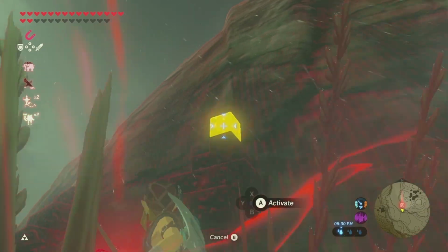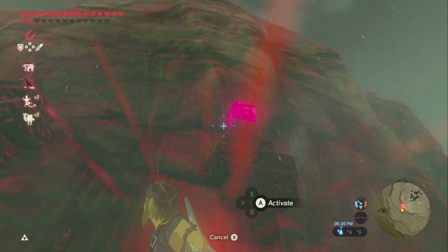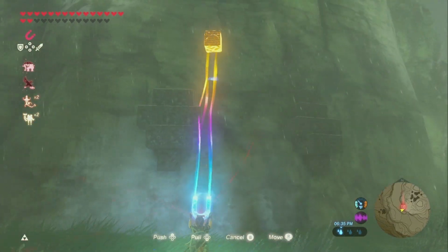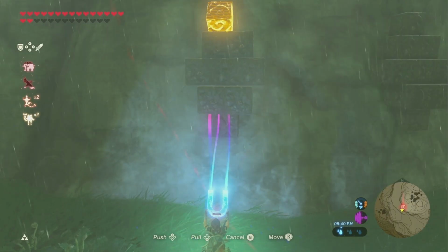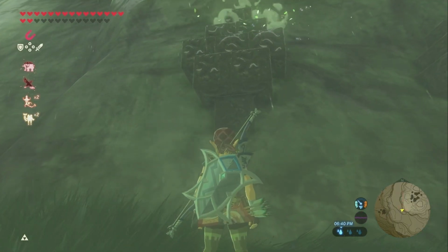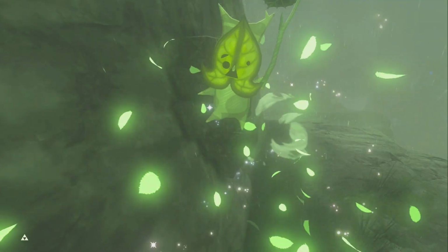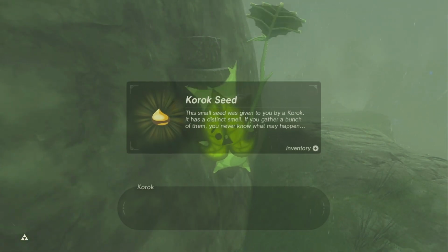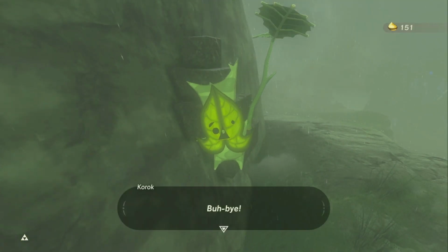Strategy: make sure that there is a drain valve and it appears intact. We do not recommend that you open the drain valve. Hot water will be discharged immediately. The other risk is that the valve will not shut off when you close it. Again, you don't want to create a leak.